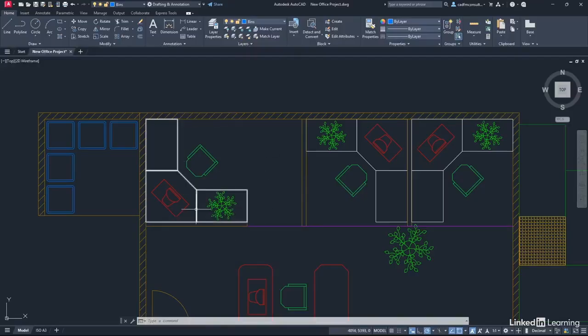Now, these blocks can be made into another block encompassing all of those objects. And we're going to create a workstation block that has all of these blocks in it. They'll then be known as nested blocks. So the whole idea is you're basically taking either objects or blocks and converting them to a block to reuse them elsewhere. And once you've got that workstation block, you can place it anywhere you like in the drawing as well. It's very quick and easy to do.